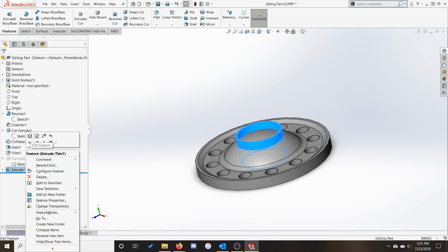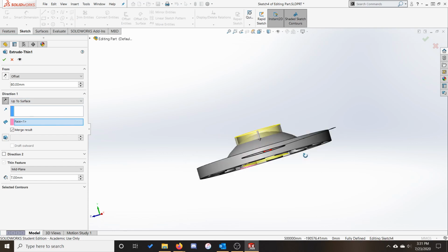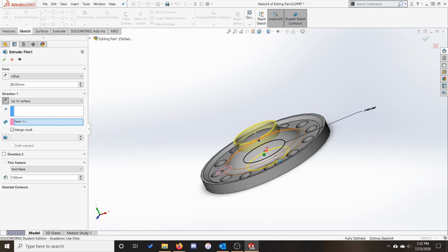We can see that this tube was made to start on an offset plane, and then extruded until it reaches this flat surface here. I want it to stop a bit earlier, say on the top surface. To change that, we can select the Surfaces box here, and then left-click on the top dome. Once again, you can only choose reference features that were created before this feature was made. No paradoxes allowed. Okay, cool. That looks about right.